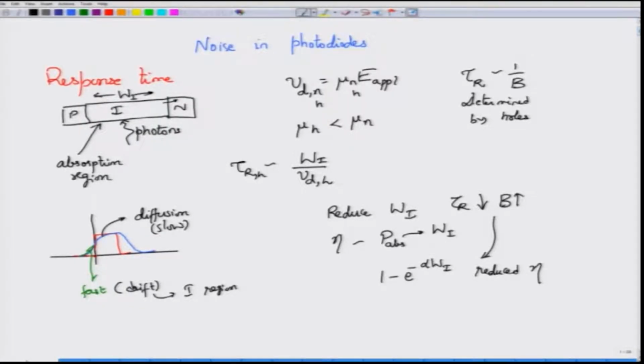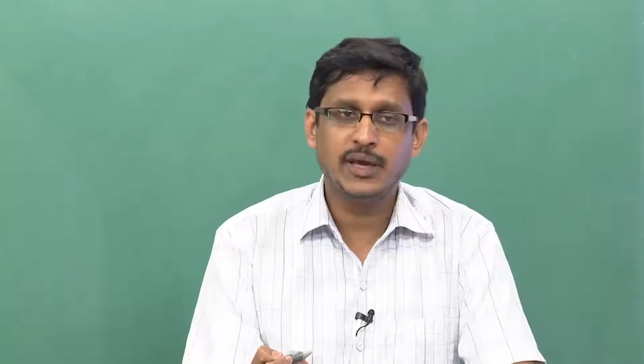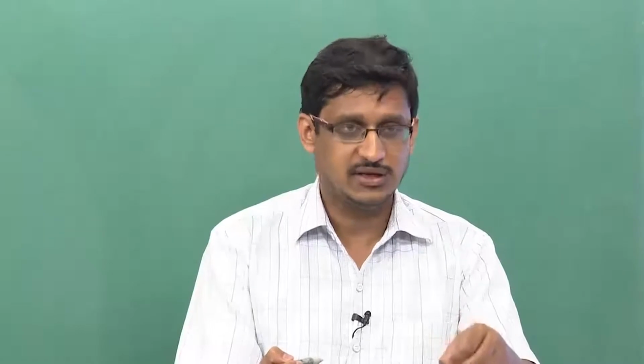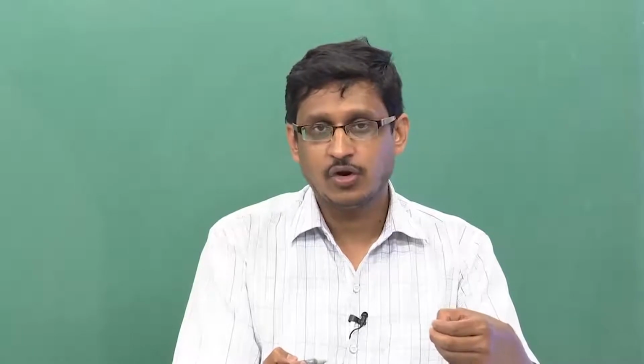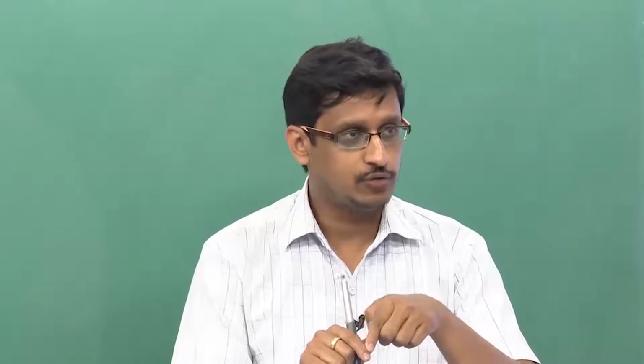We will now quickly jump over to noise processes in the photodiode. You might think that there might not be any noise when the photodiode is not illuminated. If you do not shine light on a photodiode, you think that there will not be any noise. But sadly that is not really the case, because photodetectors kept at room temperature have significant thermal energy. The materials, the atoms have significant thermal energy, and occasionally one of these electron hole pairs might be generated. And if you have reverse biased the photodiode, which you are going to do for the photodiode operation,